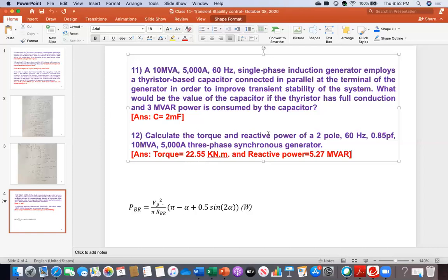And for the reactive power, with cosine theta you can convert to sine theta. It is the MVA, and you can get the active power. So Q equals root over S square minus P square. You can use the power triangle, where this is the S value and the multiplication of this is the P value. Easily you can get the Q value, or you go S sine theta in that way.